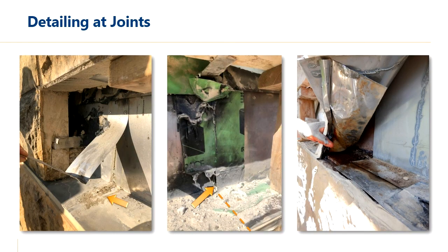We also found instances of detailing at joints being a source of water. So whether that's side laps or laps not aligning correctly and creating voids, either way we were getting water inside that was corroding or rusting the structural steel elements and shelf angles behind it.